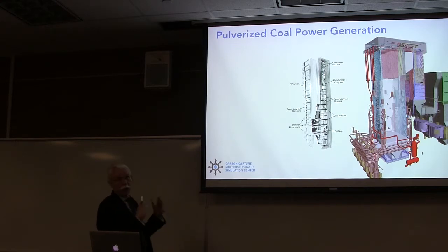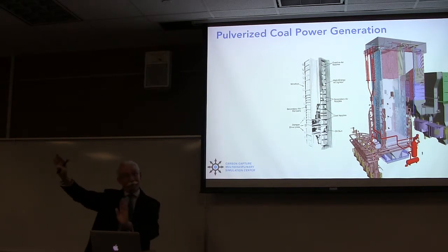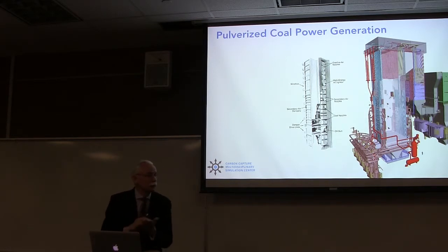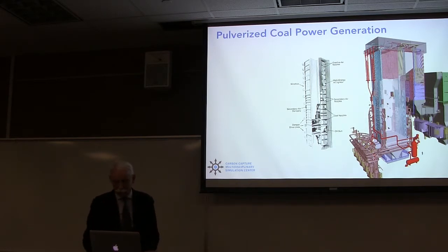This is a boiler by Alstom, as you can imagine, because that's what we're working with, who fires all of their boilers in the corners, and it looks like this. So the air is entrained into injectors at these coal nozzles with air coming in around the outside of it. The pulverized coal itself looks like about black face powder. The people who've been working on it out back can bring it in on their feet, and it's just black face powder all over.